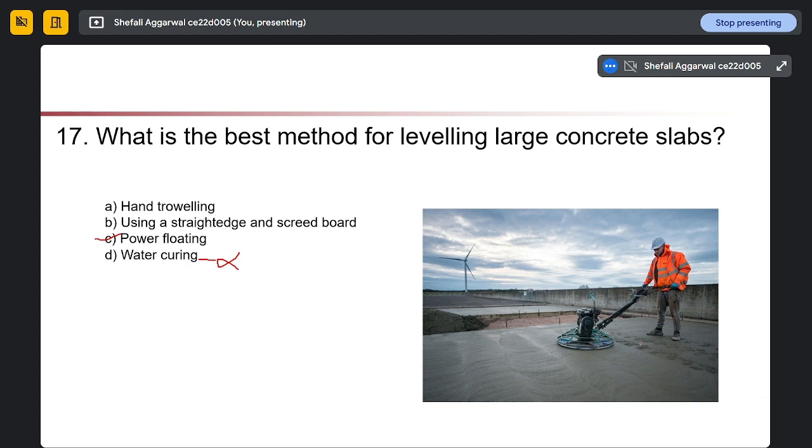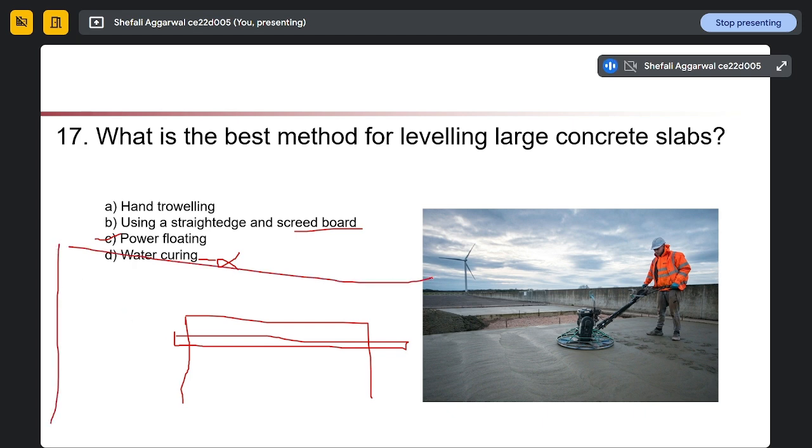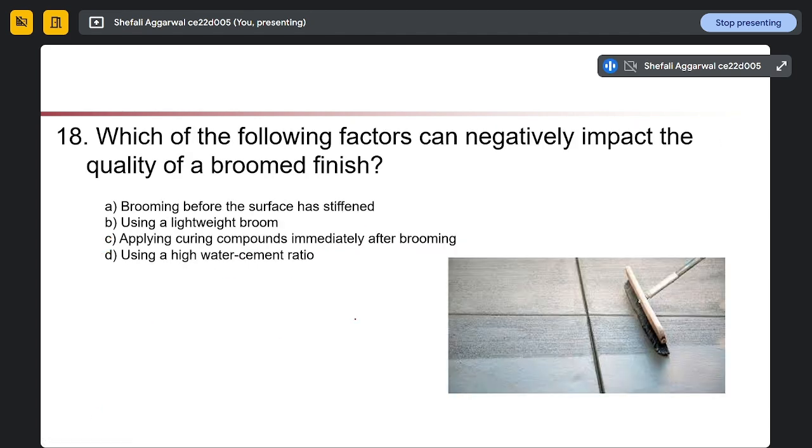Determine water absorption from fineness modulus. We cannot determine the water absorption. Show aggregate strength. Fineness modulus cannot actually show the strength of aggregate. So this is the apparatus used for the fineness modulus. We are sieving our aggregate using different types of sieves, and then we are calculating the fineness modulus from the formula given here. So the fineness modulus will give us the different grading of aggregates.